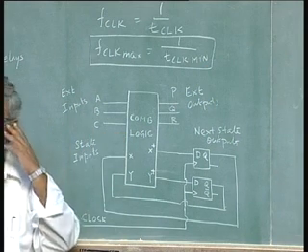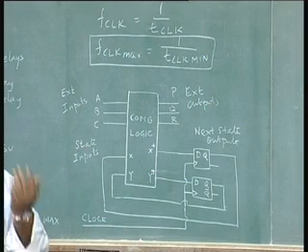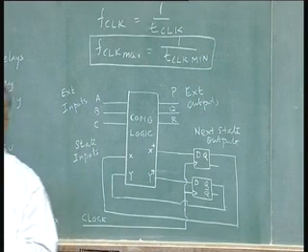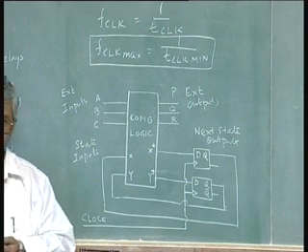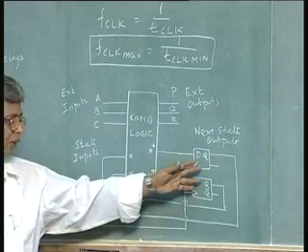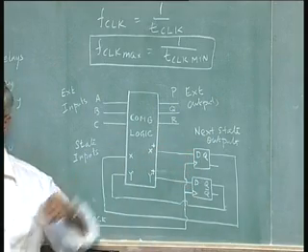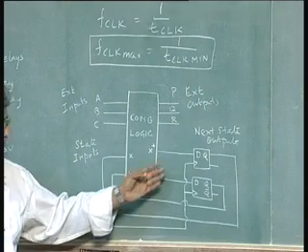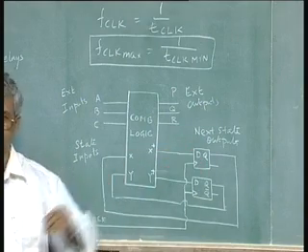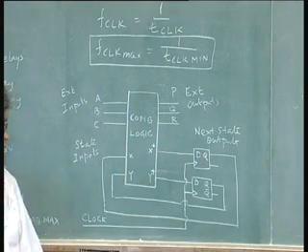Combination logic can be implemented, as you know, using gates or multiplexers or programmable logic elements, as we saw in our lectures on combination logic, and these flip flops can be any type D or JK. As I said, D is simpler because the input becomes output next time after the clock occurs.